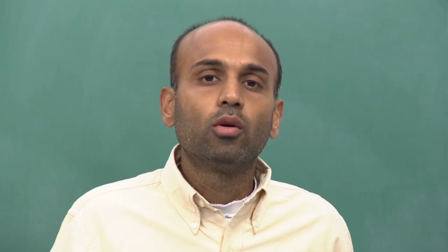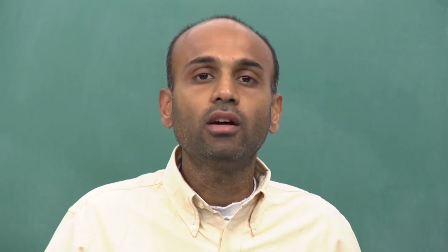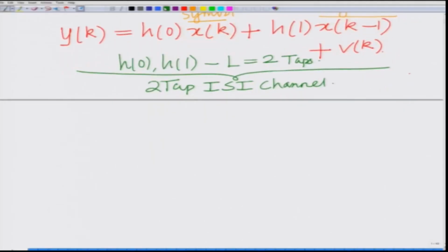Okay. All right. So now once you use OFDM, you can see that the channel coefficients across the subcarriers in the frequency domain are given by the N point FFT, in fact the 0 padded FFT of the channel taps in the time domain. And this is something that we have already seen before. Let me just write it down a bit more clearly.